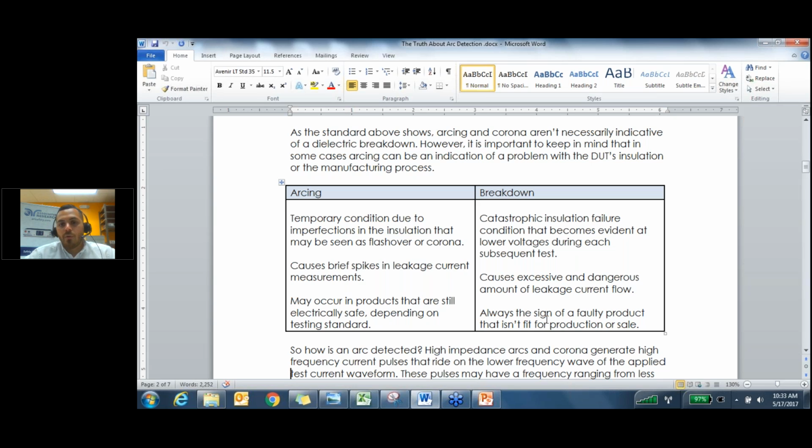Well, always is a strong word. I think, if you have a breakdown, it might have been, like we said earlier, maybe some impurities burning off. And if you run it again, you might pass. So it's always good to do a burn test. Or if you fail it, retest it again. You may have just had something in the air gap, maybe some scraps of metal in the air gap between boards, or something on your insulation that drew current, right, burned up, and now it's gone, and now you can pass your test.